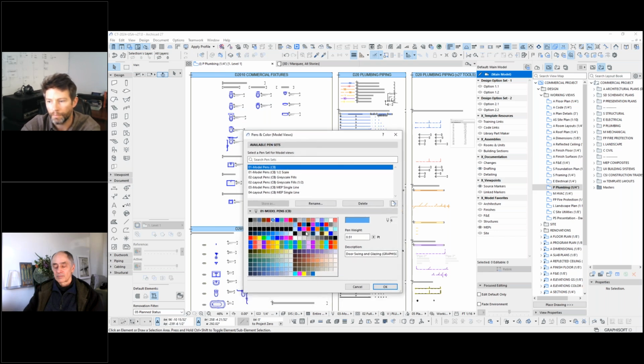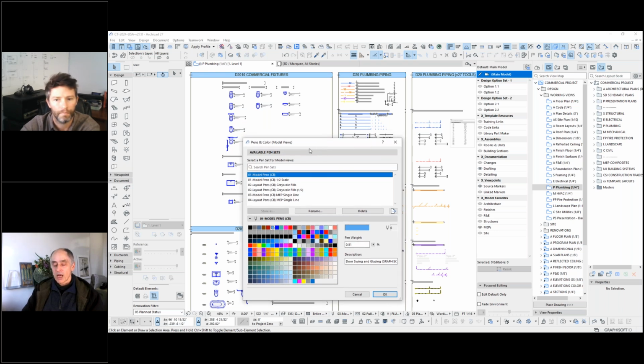Okay, the issue that I found, and maybe it's not an issue in terms of the way you're using it, is you eyedrop one type of furniture, one type of fixture, one type of element, and then you switch to a related type, then you're going to be picking up the default settings from the library.